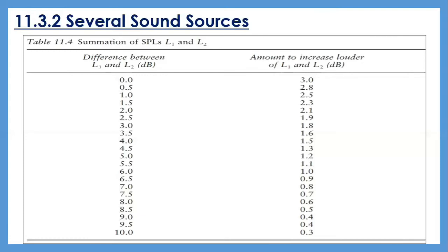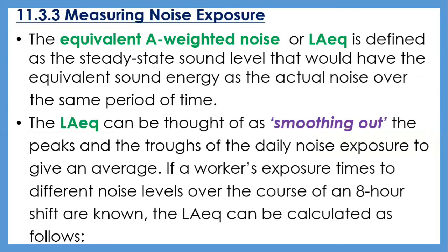And the next key subtopic that we're going to be discussing is measuring noise exposure. Remember, a number of measures have been developed to enable employees' daily noise exposure to be measured. The equivalent A-weighted noise level, or LAEQ, has been developed for those situations where noise levels fluctuate over the course of a day. It is an integrated value, the average level of sound energy over the measuring period.